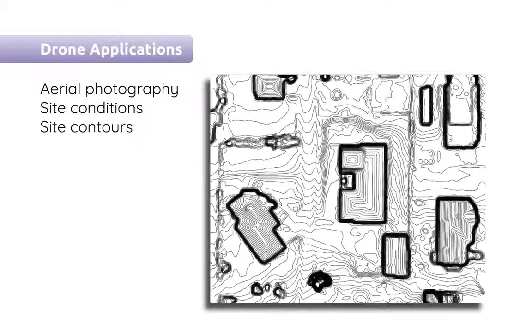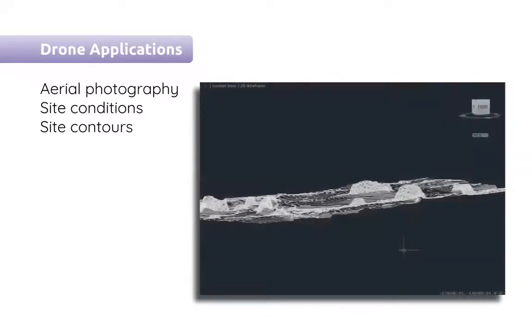Then with the photos and the photogrammetry software, you're able to generate contours of your site. These contours can then be directly imported into CAD or into a 3D modeling program to generate a landform model of your site.